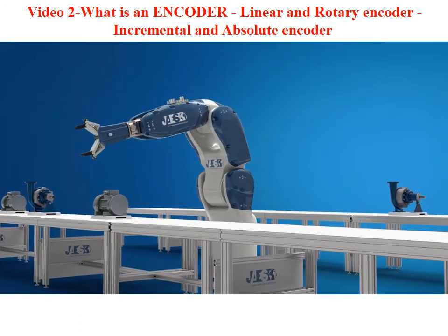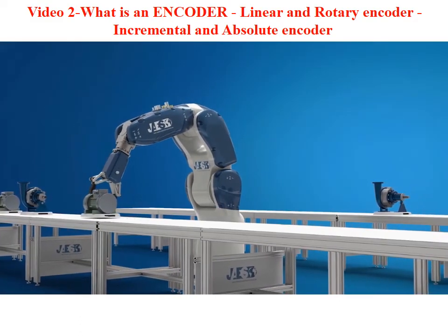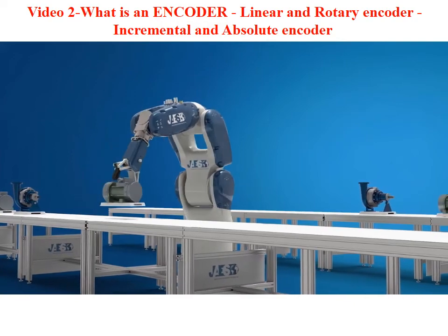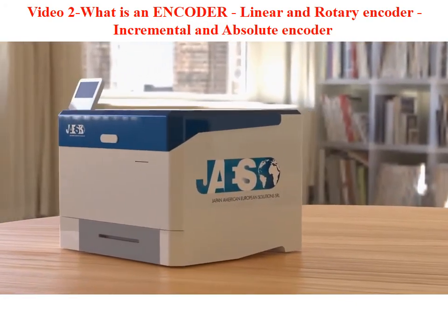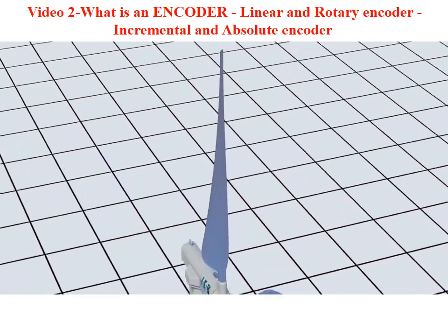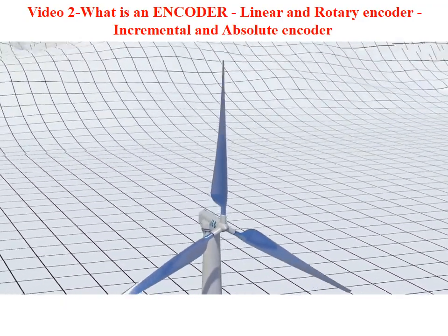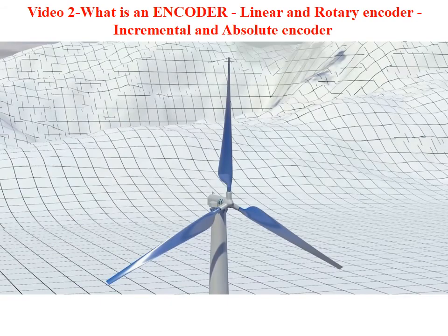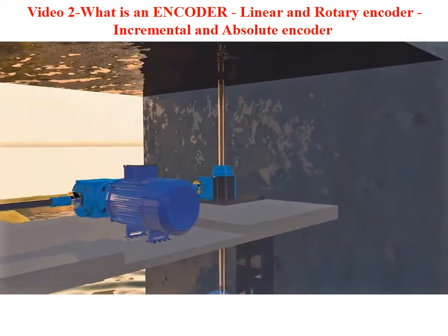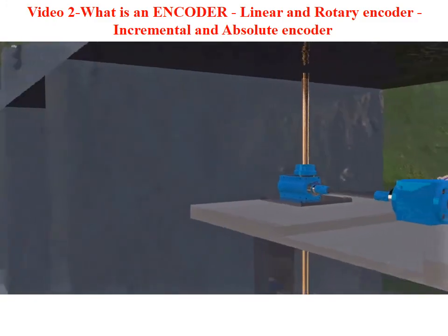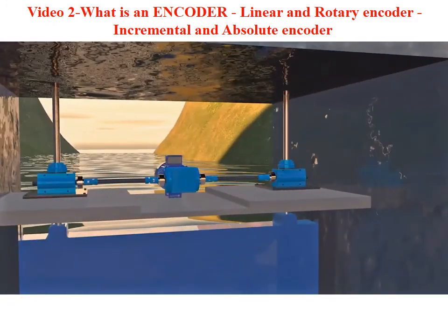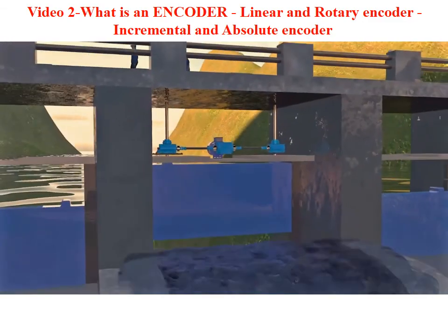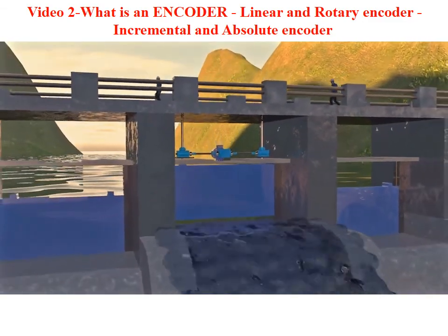We can find encoders in many robotic devices for multi-axis synchronization control, but also we can find them in common printers. Absolute encoders can be used inside the pitch control system of wind turbines, allowing the blade's angle to be adjusted according to wind speed. An absolute encoder is often the preferred solution when the device is inactive for a long period of time or moves at a very slow rate, such as fluid gate control.